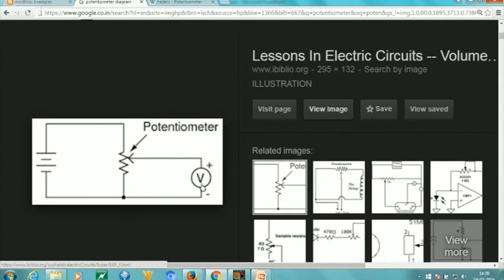So now the current is flowing through the resistance. If we measure a voltage across the whole of this resistance, then the voltage will be same as applied to it. But if we measure the voltage across a part of the resistance, the voltage will be I into R, that is I, the current flowing through it, multiplied by the part of the resistance across which we have kept the probe. So if this pointer is somewhere over here, the output voltage here will be 0. As you move the pointer up, the output voltage will go on increasing, and if this pointer is kept somewhere here, then since it is measuring voltage drop across the whole resistance, the output voltage will be equal to this.